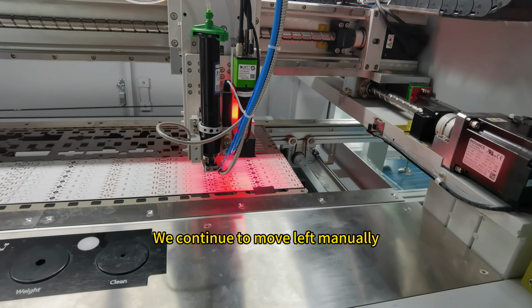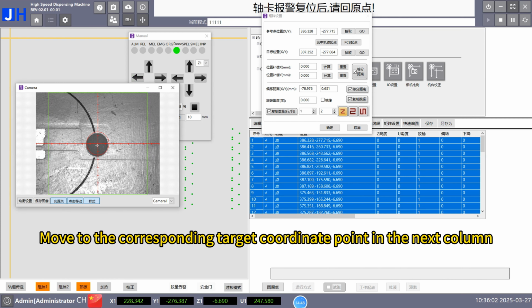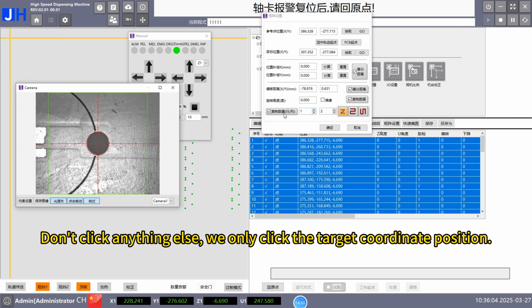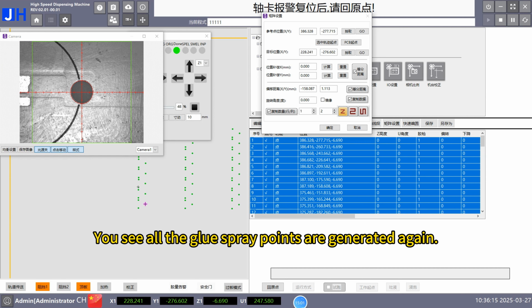We continue to move left manually. Move to the corresponding target coordinate point in the next column. Don't click anything else, we only click the target coordinate position. Do not modify any of these parameters and click OK. You see all the glue spray points are generated again.